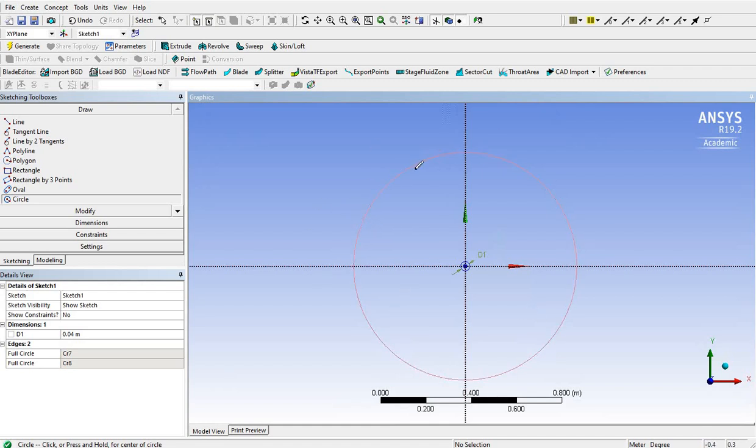Another reason you can say is that, due to the circular domain, I'm skipping some space here if you compare it with a square or a rectangular one. So I'm reducing some of the elements here, and the influence from here is not much. So it would reduce my total number of elements a little bit, maybe not, because I'm increasing the number of elements here. So it's a trade-off. But anyways, it doesn't matter if it's a circular or rectangular or square domain, as long as it is big enough so that nothing reflects from the wall. That's your main concern. Okay.